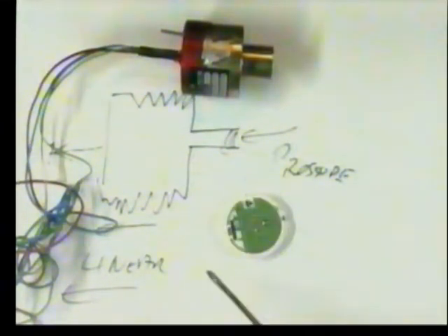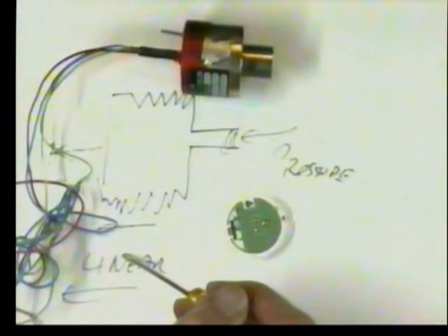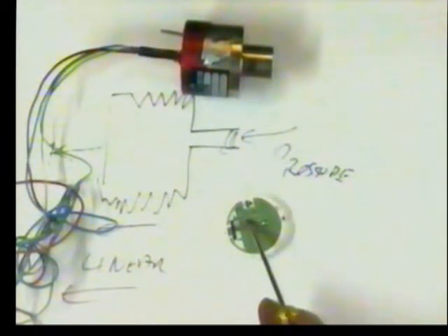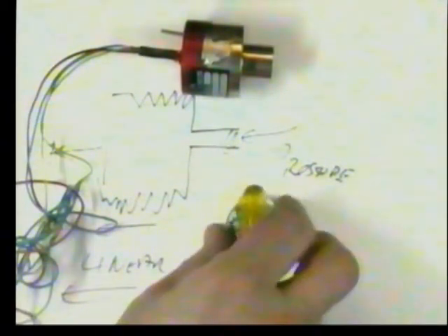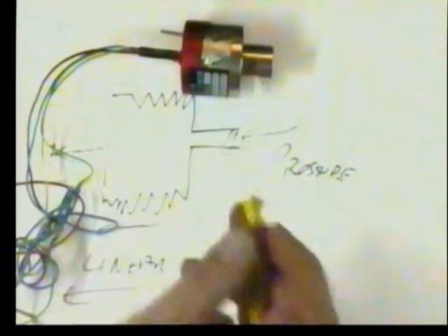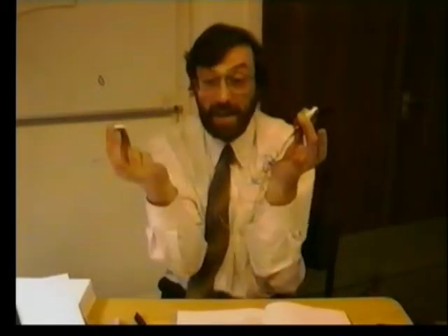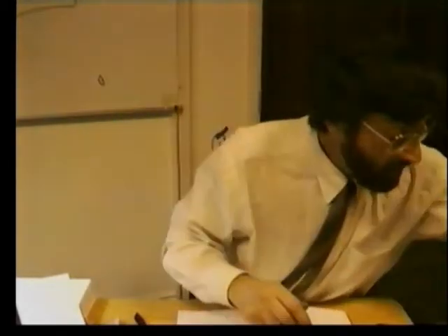They all work on the same mechanism. It's basically pressure is converted into a linear displacement. This is going to measure extremely small pressures because very small movements in the ceramic will be detected, whereas this is measuring very high pressures. Very simple concept. But what are we doing? We're just converting one measurand into another. Pressure to linear displacement.